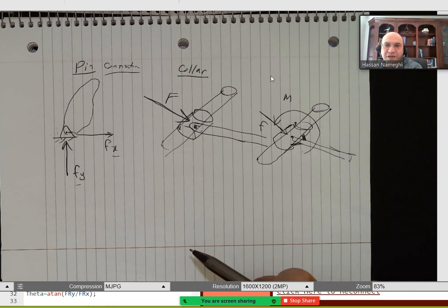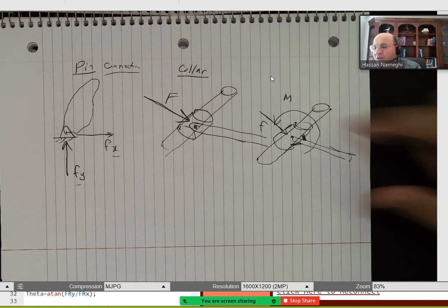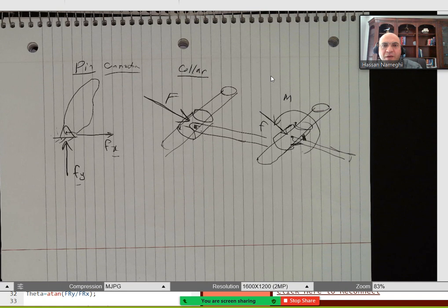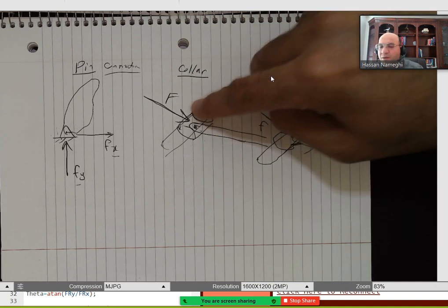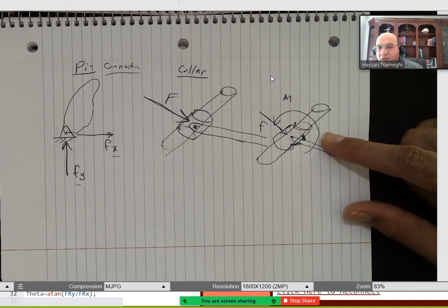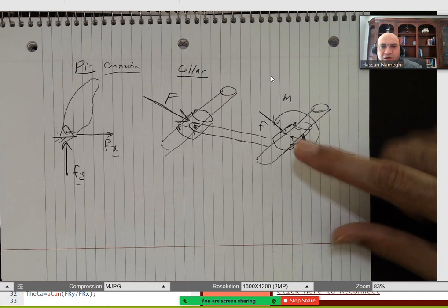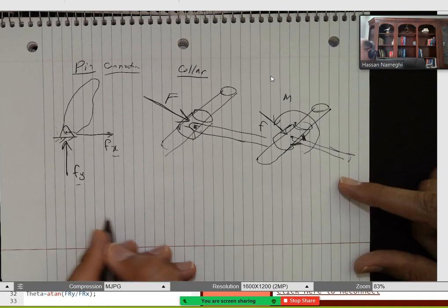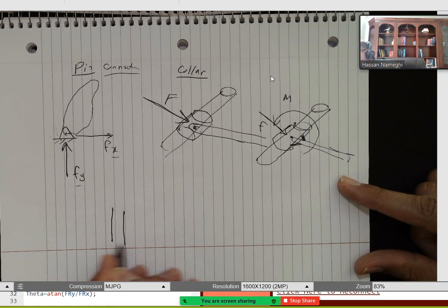Now when we go to 3D discussion, you also have 6 degrees of freedom. Here we have 3 degrees of freedom. You become limited, right? Become limited like this. It can just go one direction. This one cannot rotate, right? And it can go in only one direction. So you have 2 reaction forces. Assume something glued like this.